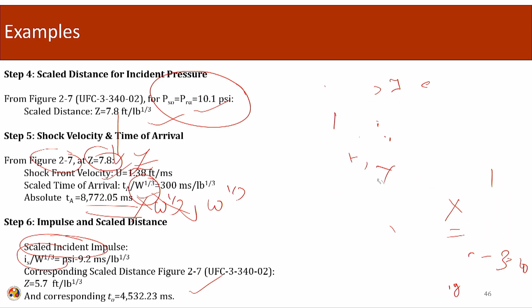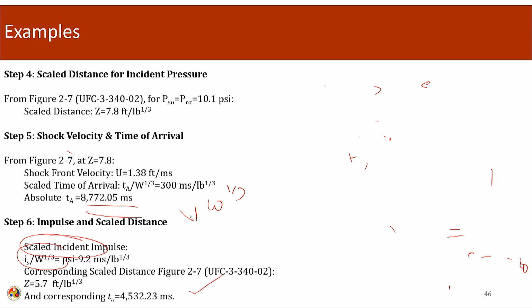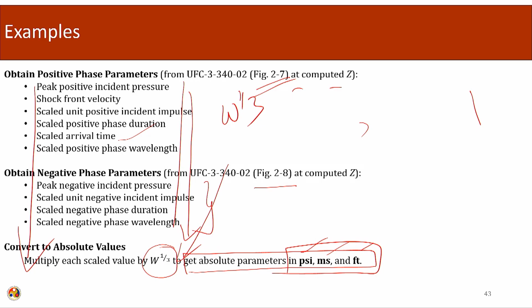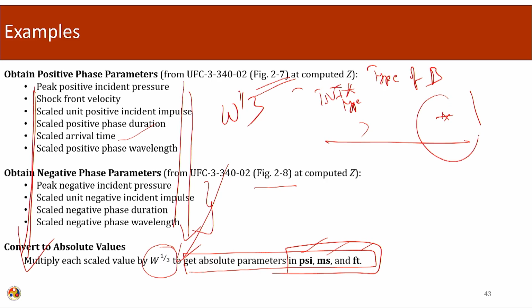What these problems are trying to do is first assess the demand. We are first trying to assess the values of the pressure, the applied pressure. All these quantities are demand quantities, which depend on the location of the blast and the point of interest, and the type of blast: surface blast, air blast, free air blast. Depending upon the type of blast and the type of explosives used, TNT or some other explosives, we are trying to calculate the demand quantities at a given point of interest.